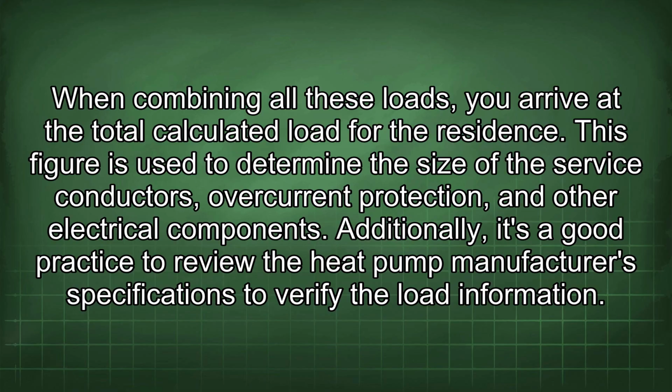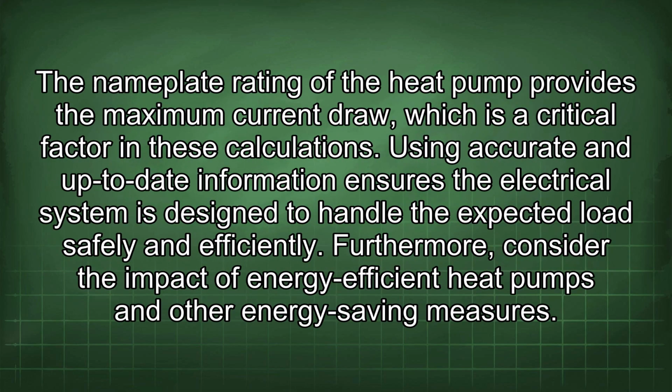Additionally, it's a good practice to review the heat pump manufacturer's specifications to verify the load information. The nameplate rating of the heat pump provides the maximum current draw, which is a critical factor in these calculations. Using accurate and up-to-date information ensures the electrical system is designed to handle the expected load safely and efficiently.